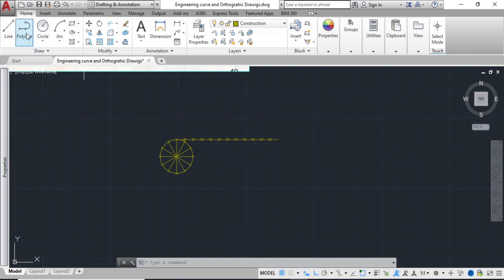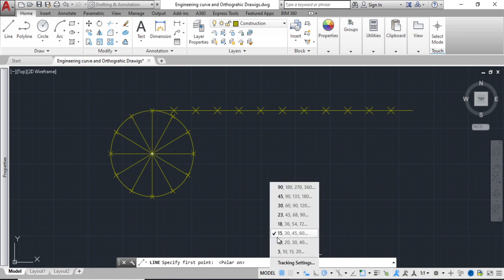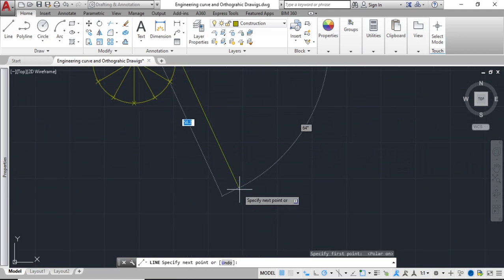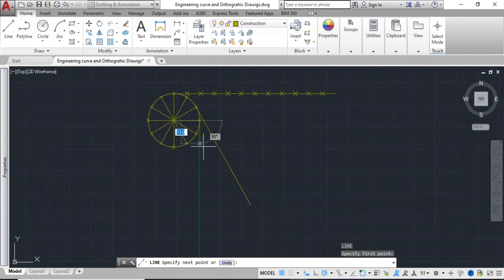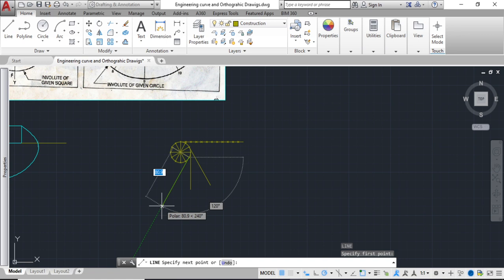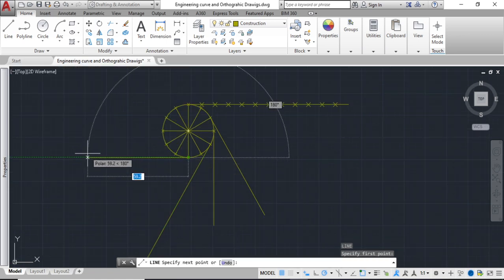So here's what I'm going to do now, is radiate my lines, my angular lines. So you turn on object snap, not polar tracking I mean. Ensure that you're on 30 degrees angular angles that can snap there. So I'll use 30 for this one. And go ahead like that. So 90 degrees that way. Boom. 90 degrees that way. 90 degrees that way. 90 degrees that way.